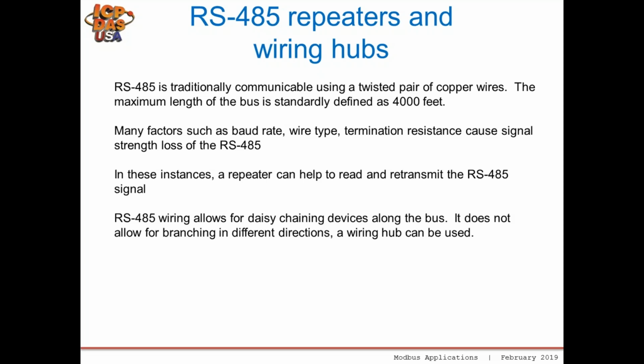And RS485 wiring also allows for daisy chaining multiple devices along a single bus. It does not allow for branching in different directions. In this case, a wiring hub can be used. I'll give you some example pictures in a second.